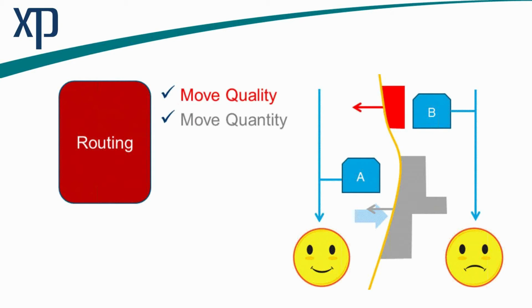If you have dense areas with multiple treatment systems, it could be possible that if catchment B in this particular example is exceeding its capacity, maybe we could divert somewhere in the network and push over into catchment A to better equalise and offset a future upgrade of key infrastructure, and then at a later date cancel that connection and undertake our major infrastructure upgrade, but possibly 10 or 20 years down the track rather than up front or as part of a major development.